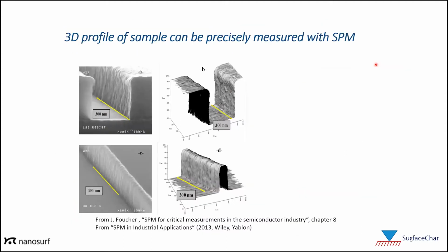And then just one industrial application where these topographic measurements are really key, and that is the semiconductor industry, where they use AFM as a quality control tool for critical device metrology. So they've got these features in their devices, these trenches, for example, here, and they have to very accurately measure the width, the depth, the roughness along the floor, the sidewall, and up here. And the three-dimensional topographic maps that AFM can construct are extremely useful and important. Like I said, AFM is a main control tool for